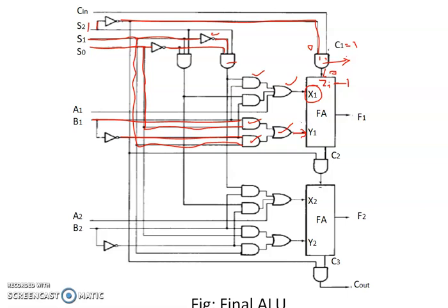So these are the inputs of the full adder circuit. Based on the n-bit ALU that needs to be designed, the full adder circuits will be cascaded to implement the same. The output of each full adder will be fed as an input to the next full adder.